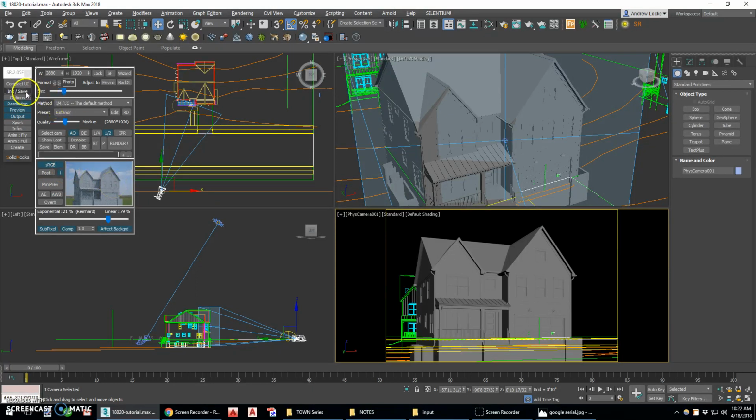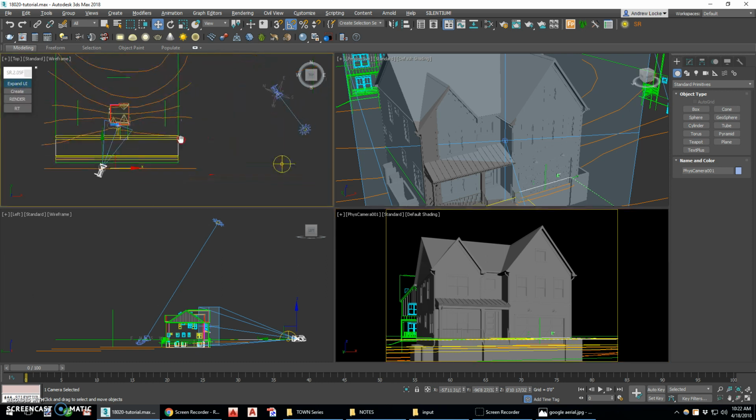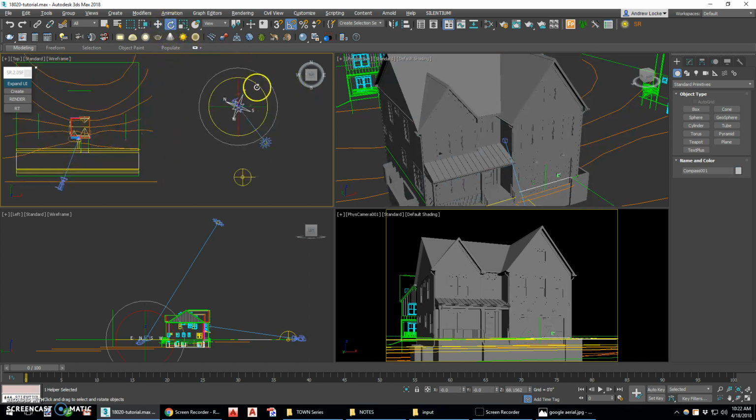The only other thing we're going to do here is go ahead and adjust the sun to be real from the correct direction. So what I'm going to do is click my compass rose here and rotate it. I happen to know this house faces just a little bit more westerly, just a little bit south. So I think we're rotating it 15 degrees. I'm going to note that.